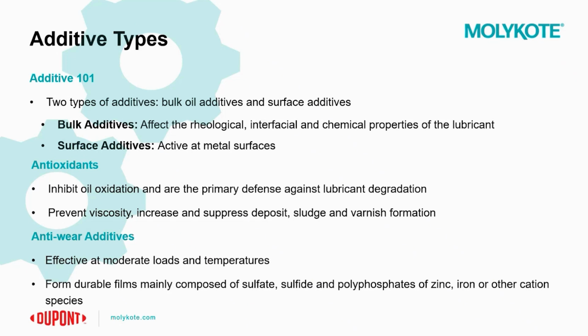Also, you can incorporate anti-wear additives into a formulation. And anti-wear additives are different in that they are most effective at moderate loads and temperatures. So again, it's important to consider the application requirements when considering the additive that is being incorporated into a formulation.